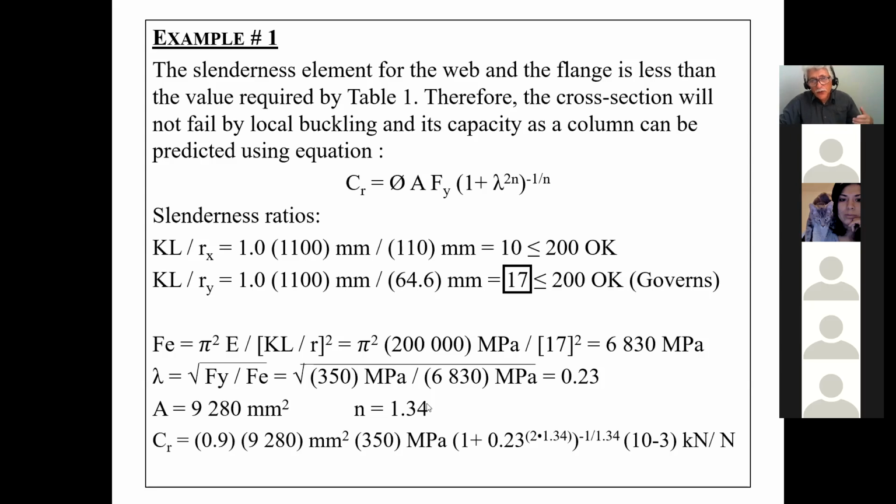It's very simple. First of all, the other one is just for HSSs and welded wide flange sections. Are we using welded wide flange here? No. Are we using a HSS? No. So therefore I know I got to use 1.34. I can go back to the first slide and read it again, but when you review the slides, you can go back and read again where N is used.